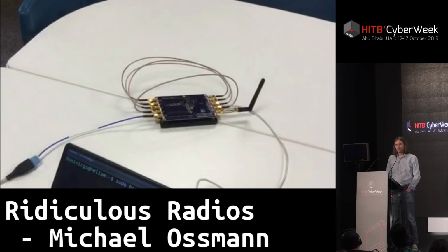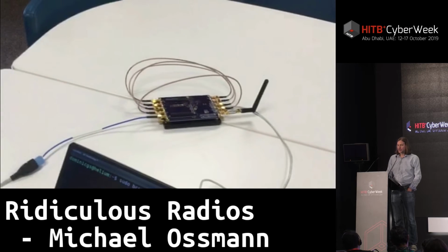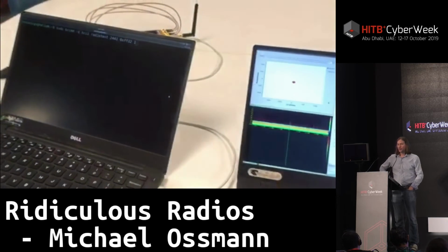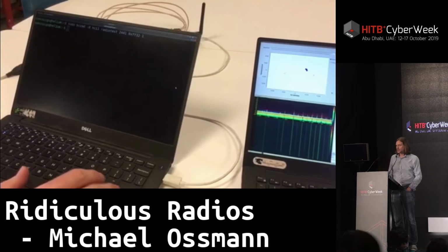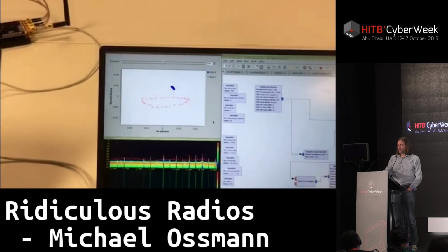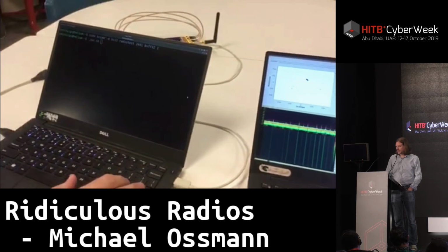That's the Bluetooth dongle that he's configured to generate this test signal. It's going through the Opera Cake that has multiple cables of different lengths connected. He's only using 2 of those, even though he has 4 connected. And then into that transmit antenna, that little black antenna on the right-hand side of the screen. And so he's going to transmit a signal without switching its phase randomly. And you can see in the upper left-hand corner of my screen that there's this blue dot that indicates the direction of that signal. I'm detecting the direction of his signal.